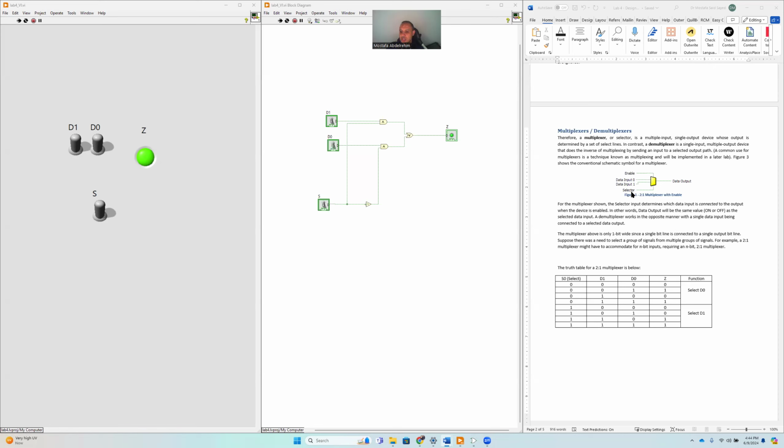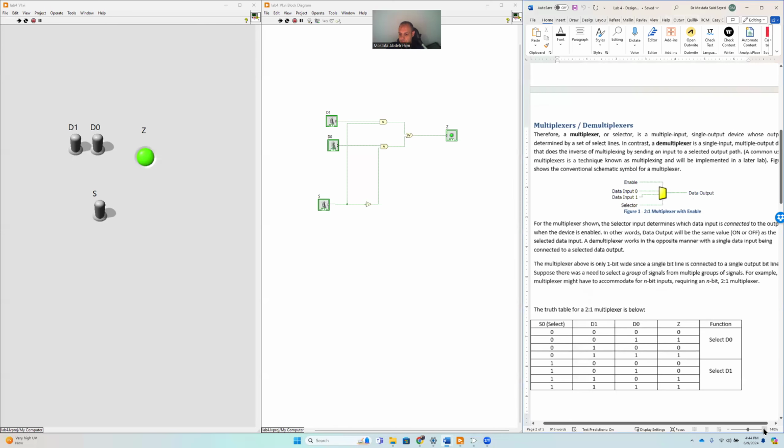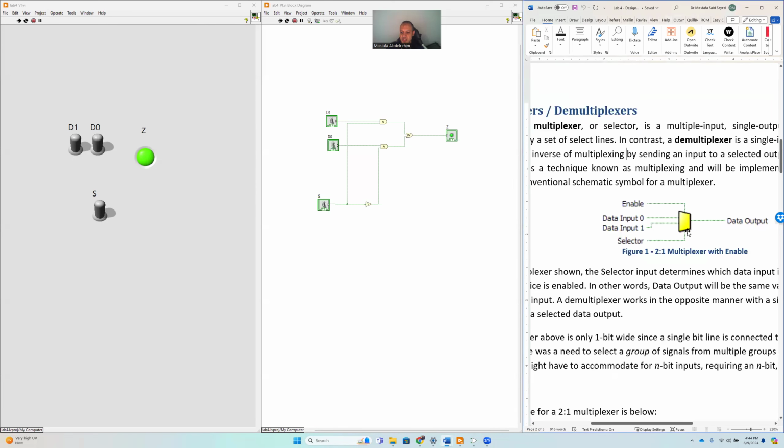Okay. So the multiplexer basically does the following. Let's assume this yellow box is the multiplexer. Of course this yellow box should have AND gates, OR gates, logic gates in general, but this is not our problem now. So how does it work? Assume this circuit is enabled. Enabled means it's operable, it can do the function. And this usually happens if this enable input is equal to 1.